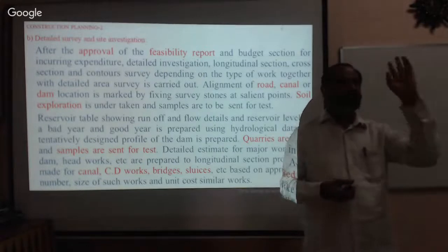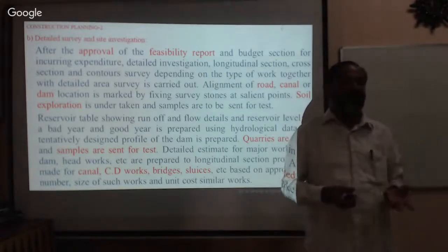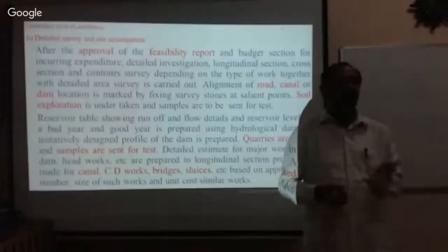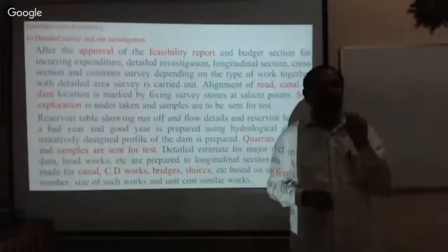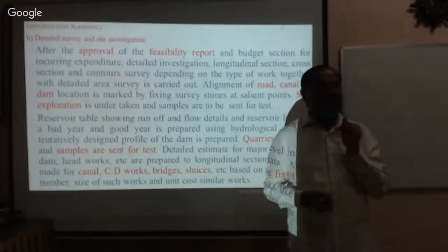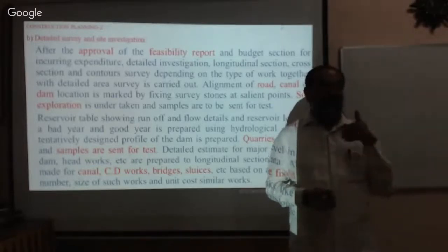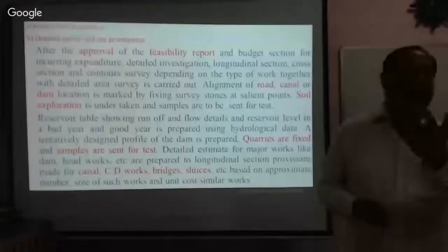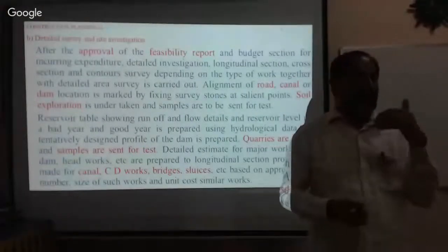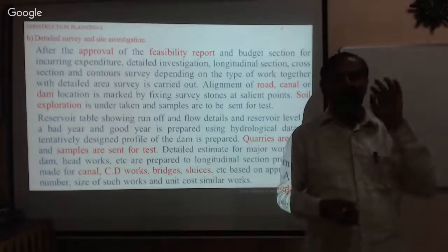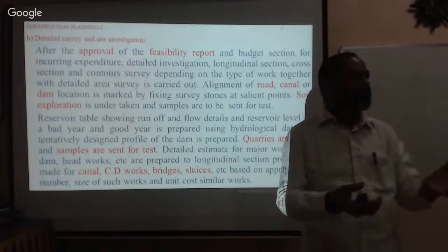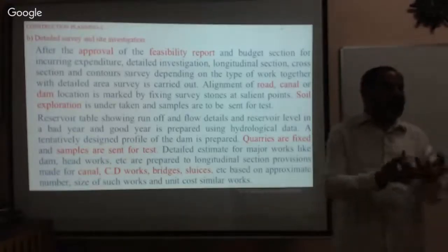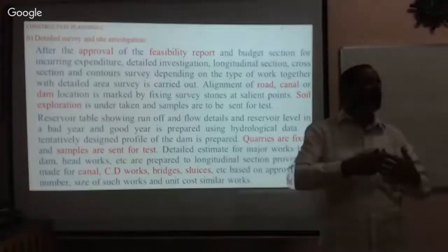Whatever the details you want to implement in the project, you conduct it. For example, if you want to construct a road, then you need to take the center line, the longitudinal section, then the cross sections, then the cross drainage works, bridges, valleys, flyovers, isn't it? All those things should be assessed and the detailed drawing report prepared.